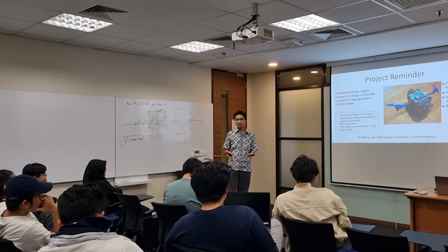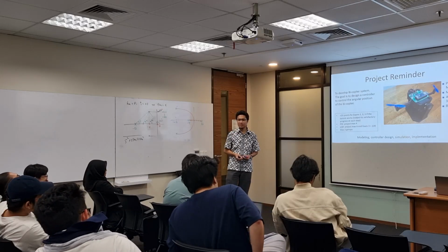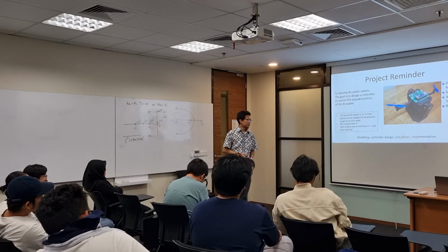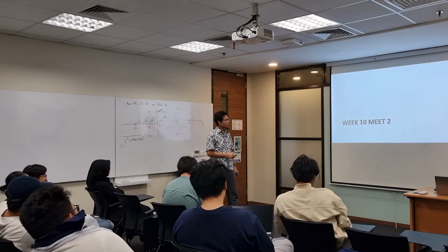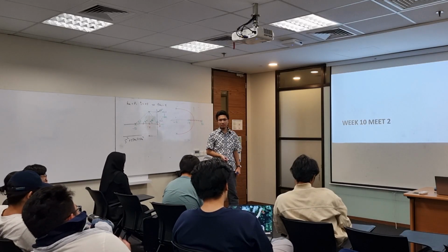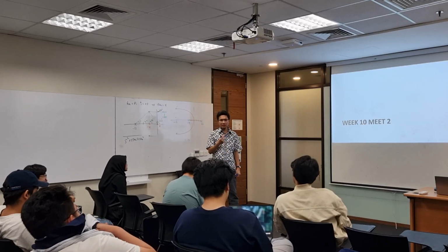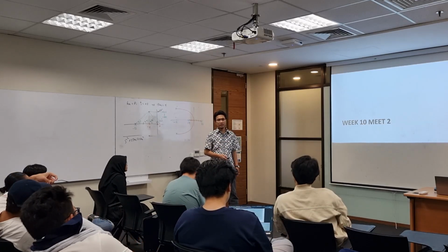Yeah, the time in here is not permitted. Too constraining. But PID is still okay. PID is still okay. One input, one output. Your system is single input, single output, so you can use PID.